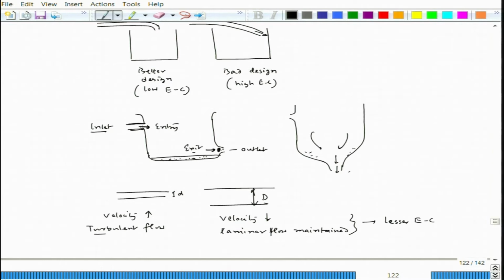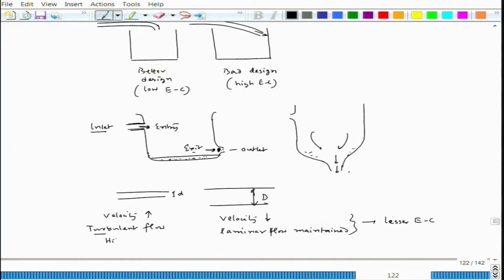Now, why are we making this comparison? For example, if this pipe is carrying some fluid and the flow rate is such that in each hour we have to accumulate 100 kg of that fluid in a bucket, then definitely the speed at which the fluid should go through the smaller pipe diameter would be much higher. So, that would lead to a higher EC, higher erosion corrosion, fine.